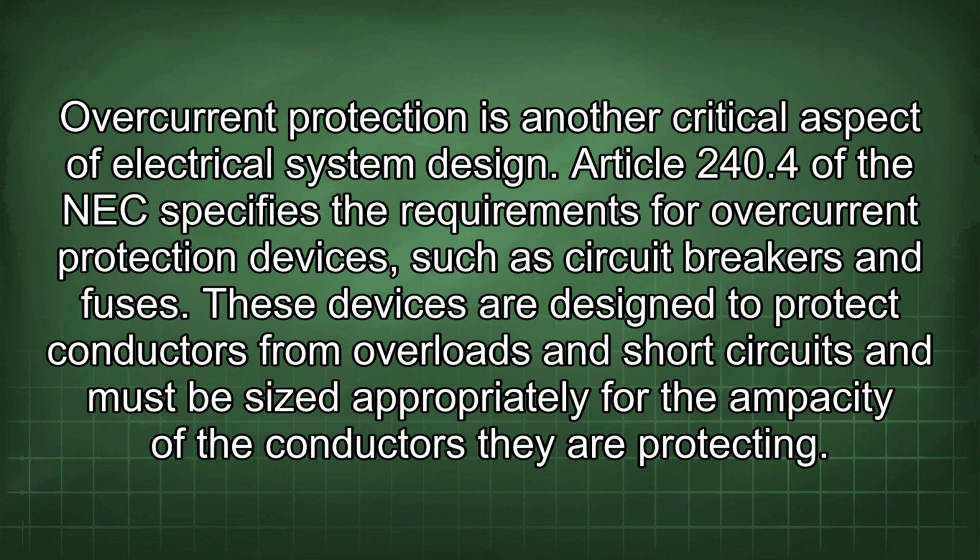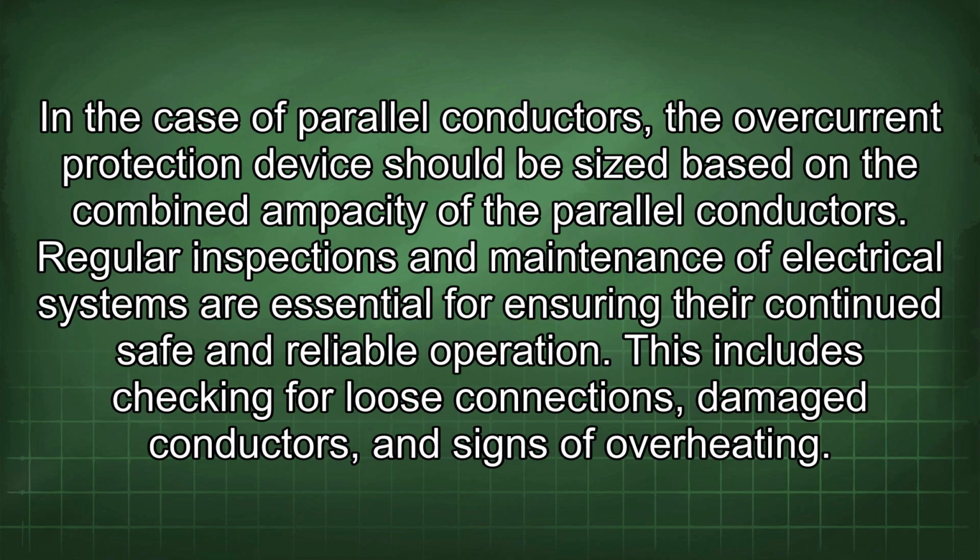Overcurrent protection is another critical aspect of electrical system design. Article 240.4 of the NEC specifies the requirements for overcurrent protection devices such as circuit breakers and fuses. These devices are designed to protect conductors from overloads and short circuits and must be sized appropriately for the ampacity of the conductors they are protecting. In the case of parallel conductors, the overcurrent protection device should be sized based on the combined ampacity of the